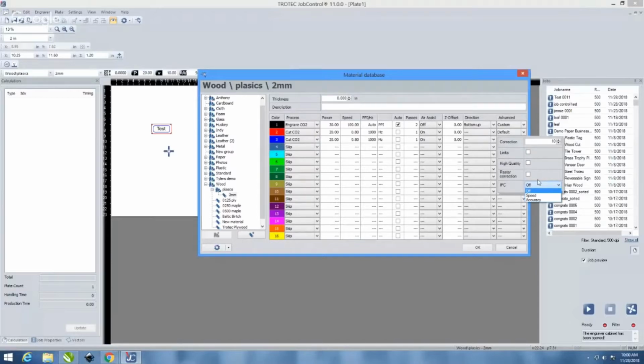Sticky edges are usually more due to the frequency being used for the cutting. So you want that on engraving plastic to be as low as possible. So 1000 is really where you want to be for that. If you're trying to cut it at higher frequencies, you're definitely going to get a stickier edge for sure. Position on the plate doesn't really play a factor in that. Perfect.